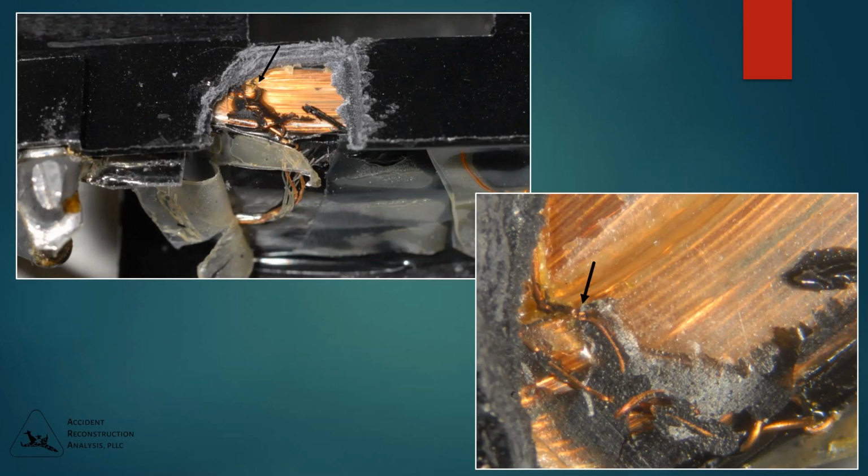So we began taking apart. The failure was actually beneath the plastic bobbin, so we had to cut and remove portions of that bobbin to access the failure location, which is shown at the bottom right. You don't make out a lot of details, but the actual break in the magnet wire is marked with the black arrow. And it appears to be embedded in some sort of varnish or resin, so it's not like it was exposed and could have been damaged during handling. So this would be a manufacturing defect then. Yep.